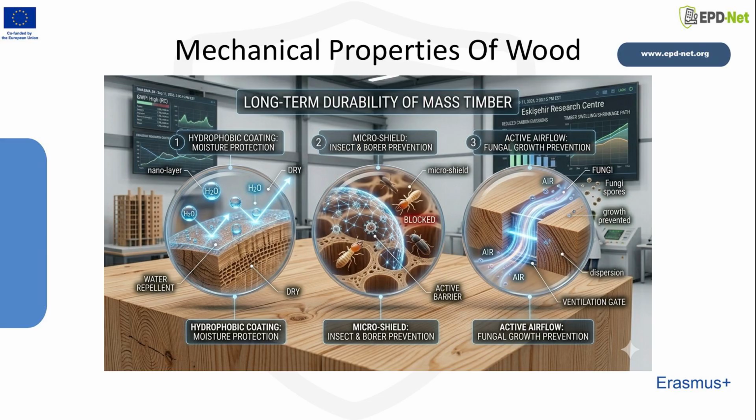Safety stresses are another important concept. Laboratory resistance values cannot be directly applied to real structural conditions. Natural defects, environmental effects, humidity changes, and long-term use must be considered. Therefore, safety factors are applied to determine allowable stress values and ensure safe use.